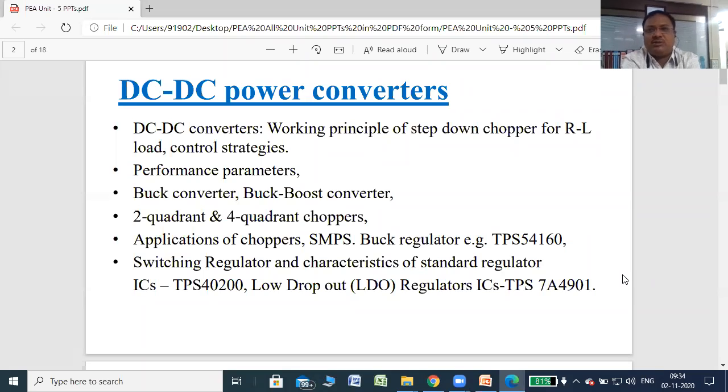Now in unit number third, we have started with the applications of power devices. So first application that we have seen is AC to DC converter, right? That AC to DC converter basically has an AC input and a DC output, that is a variable output. So output is changed or you can vary with the help of changing firing angle. As you increase or decrease the firing angle, you have a variable output voltage. So that is the one part.